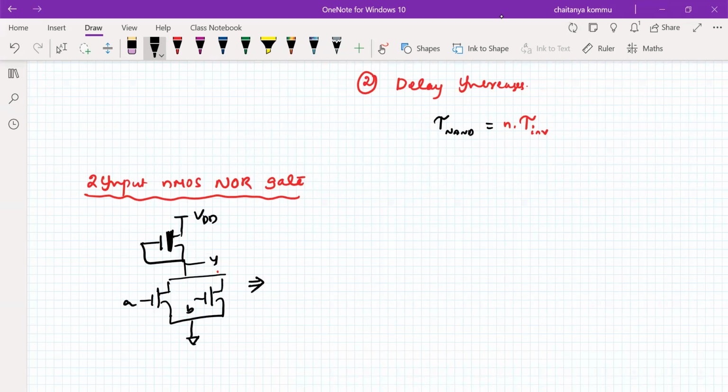So what is happening here? Since these 2 lines, for example, if this line is connected to ground or this line is connected to ground, from VDD to ground there are 2 possibilities. One possibility is that it can go this side, or the other possibility is that it can go this side. So it is similar to the inverter characteristics depending upon the input application. We observe it maintains the same ratio, a 1:1 ratio on both.